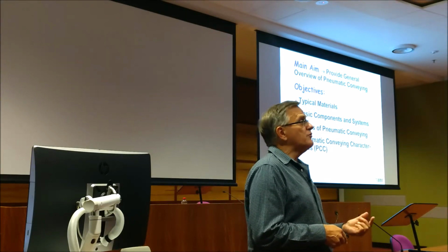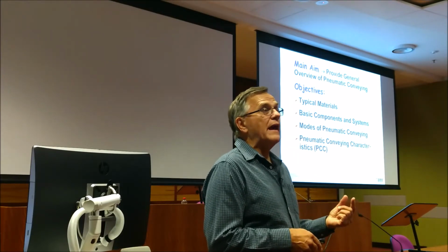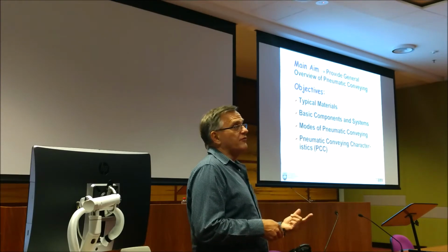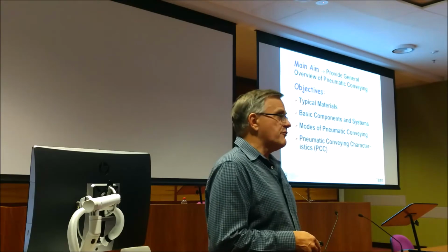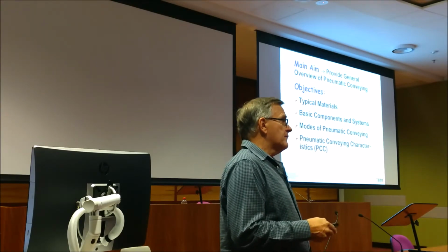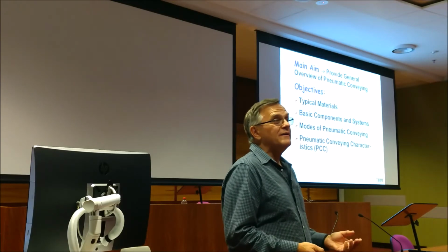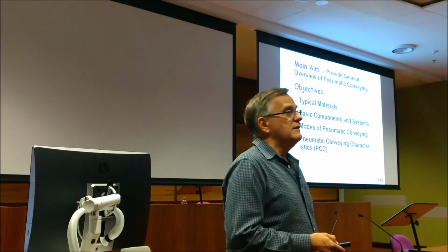The mathematical models that are out there are not that accurate, depending on how you're conveying the product and the type of product. But if you do some tests on a representative sample in the laboratory, then you know at least that data is accurate for that product. But quite often, in the industry, if you want to do 100 tonnes per hour, in the lab you can only do 2 tonne an hour, then you have to what we call scale up the information.